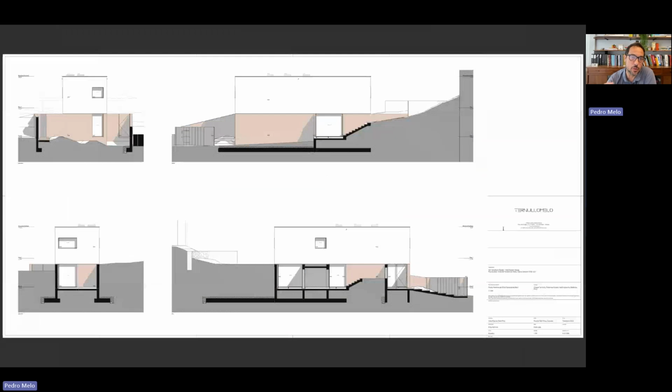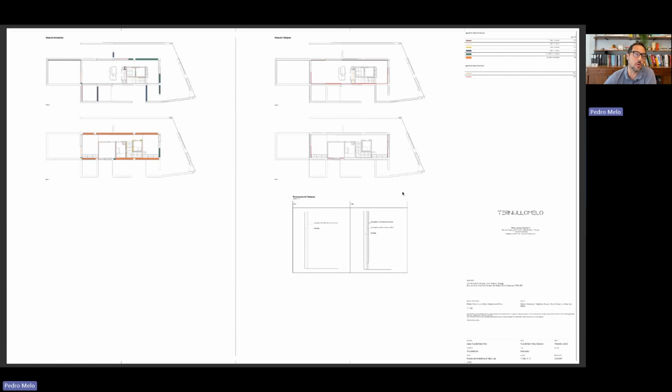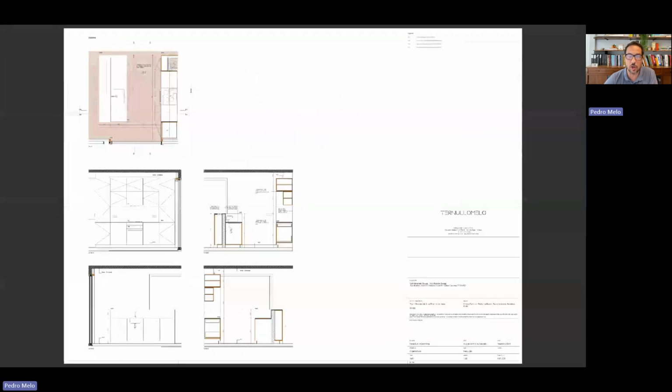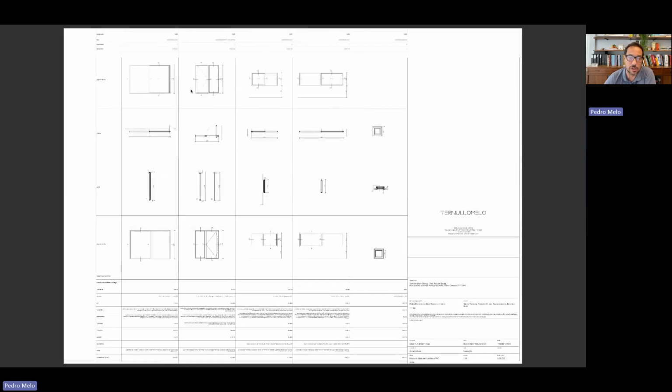So the template was built to produce this in the fastest way possible, okay? The project is something where you cannot control the time it's going to take, but the documentation is something where you can waste less time. All of these, for example, the way we explain finishes, wall coverings, the walls, all the floors, the ceilings, it's mostly automated, okay? We have a rule, a way of doing stuff, and we always do it the same way, okay? All of this documentation is produced almost automatically from Archicad, because there's also always some 2D work, of course, mostly labeling and dimensioning.